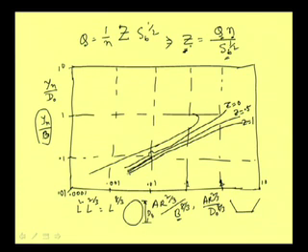Then this part is becoming narrow, this is not changing that much, but here it is changing, z equal to 1.5, and z further increasing, z equal to 2. Like that, with the increase of z value, that means the side slope z. Well, do not confuse this z and that z, I should have used a different symbol here. In this graph, for section factor let me put z1, okay, and this z is representing side slope. So, this z is side slope, and section factor I can write as z1. Here of course I am not writing any symbol for section factor, I am writing A R to the power 2 by 3 directly. Well, so that way we can have this curve.